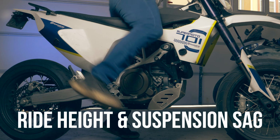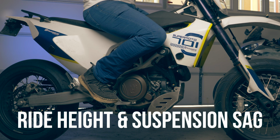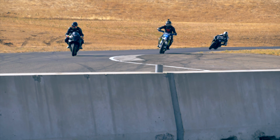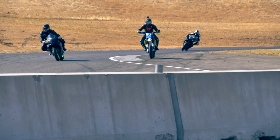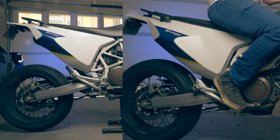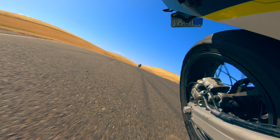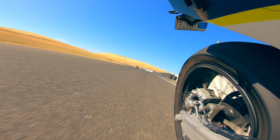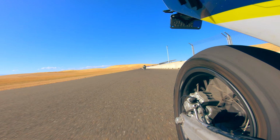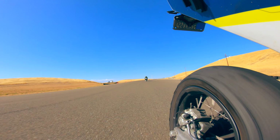The spring rate and preload also affect something very important, and that is the ride height as well as the suspension sag. Now you already know that the ride height has an effect on the motorcycle's geometry, which will alter the turn-in as well as acceleration phases of cornering. Suspension sag refers to how much the motorcycle's suspension compresses from fully extended with the rider on board. This compression is very important because it enables the suspension to extend down into dips and depressions in the road surface. Without suspension sag, the tire would lose traction going over these dips.